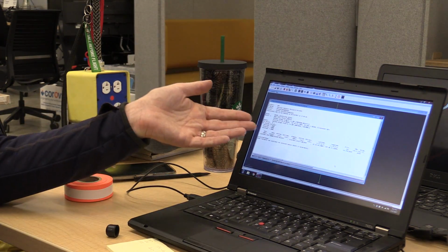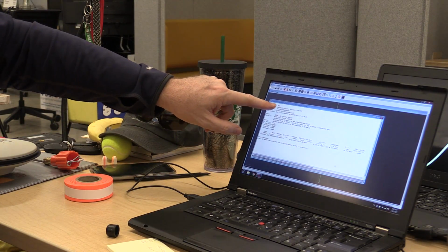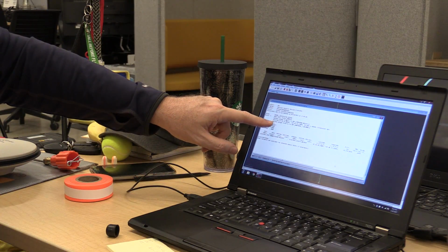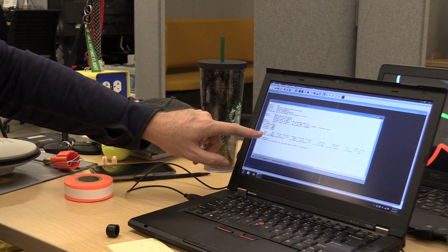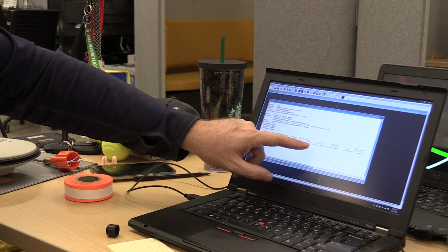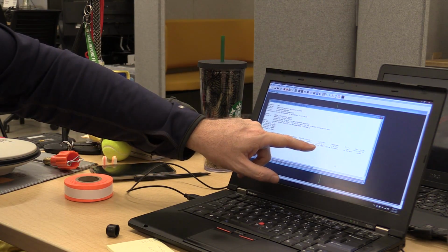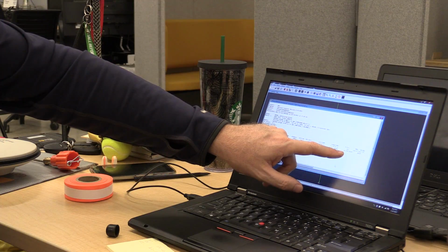Okay. So this is the product we're trying to produce. Up here, it says our project name is BD1, which is also our point name. And then it gives us information about the site that we compared our data to and collected error information from. And then down here at the bottom, it gives us our particulars about our point. It tells us that our point is located at this latitude, this longitude, with this height above ellipsoid in meters, which identifies as negative, which is common around here, that we see negative points.